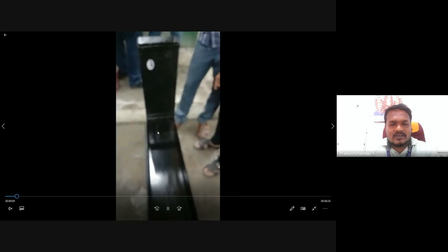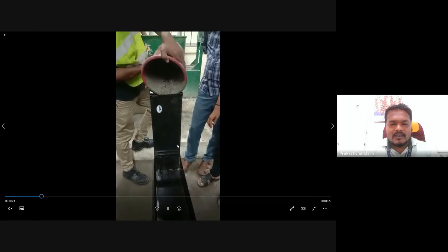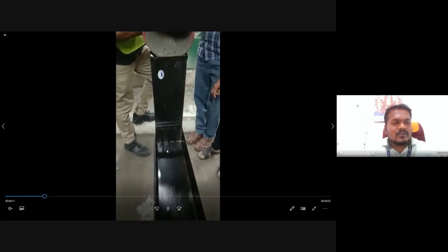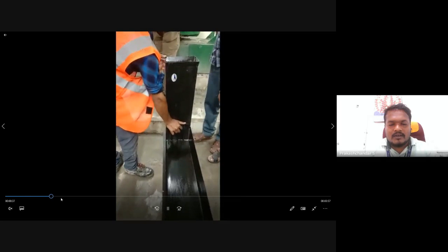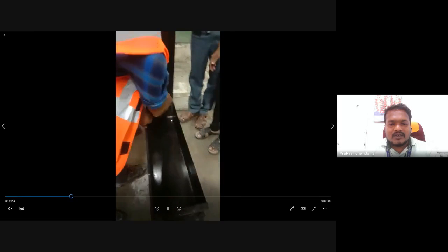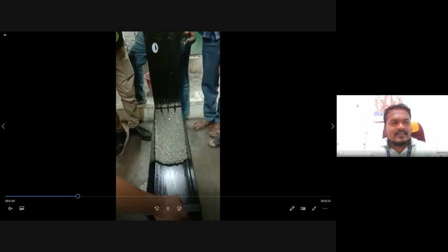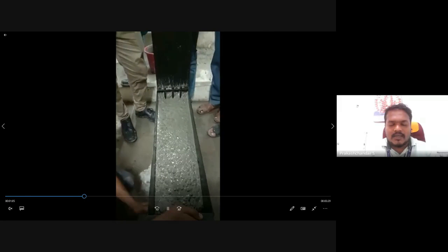Okay, this is for the L box test. So here, you can fill the concrete in the L box test tank, and see here there is one gate valve. This is H1, and the opposite side is H2. After the concrete is fully filled, remove the gate valve. This is the L box test for passing ability, and the formula is H2 by H1.